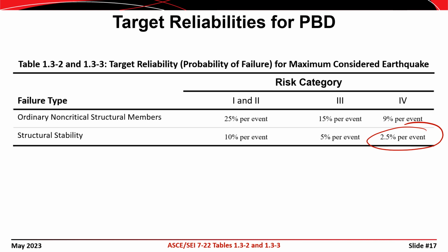And it just goes to the fundamental philosophy of design in that when we look at performance of a building on a day-to-day basis, we shouldn't have any buildings failing under normal snow loads, rain loads, live and dead loads, or even under routine wind events. But we're willing to tolerate the failure of a significant number of buildings under earthquakes, right? A maximum considered earthquake. Now, why is that? Well, two things, really. This is a maximum considered earthquake, so it's an earthquake that's going to occur every 2,500 years. So the odds of it occurring during the life of the structure are fairly small.